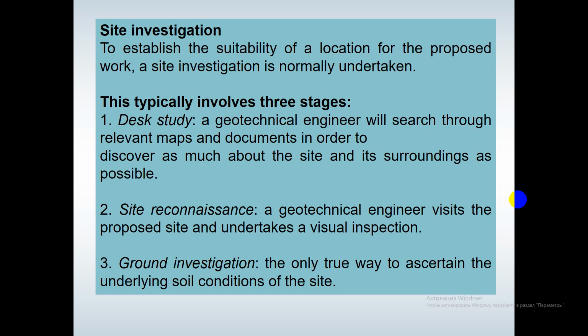This could be in a disturbed or undisturbed state, the latter representing the exact in situ state of the soil, for example in terms of moisture content and degree of compaction. The soil samples are normally extracted from the ground by drilling some form of boreholes or excavating a trial pit.